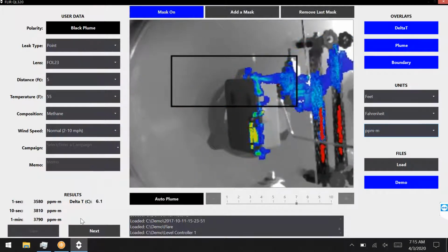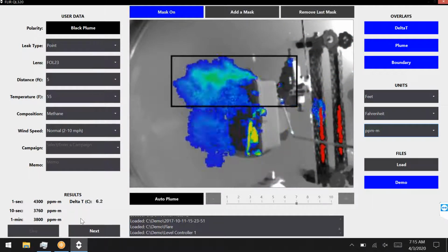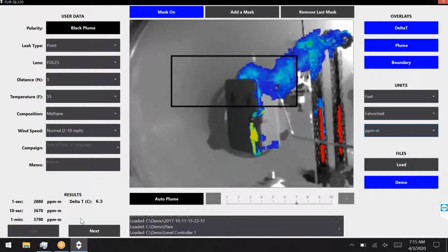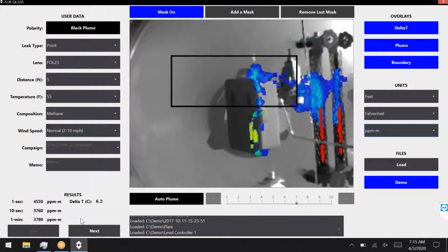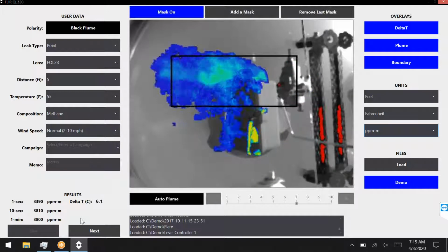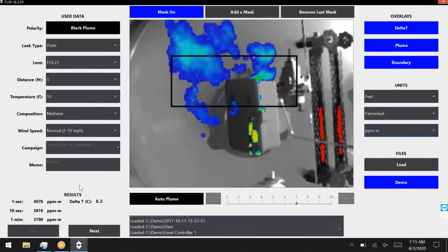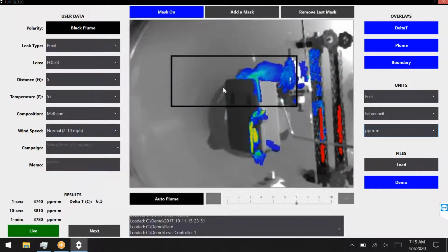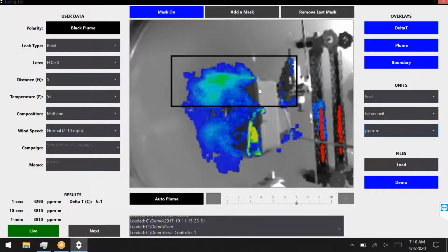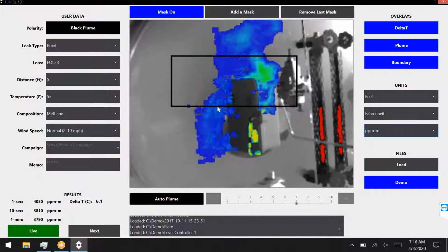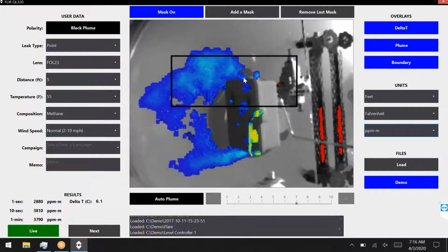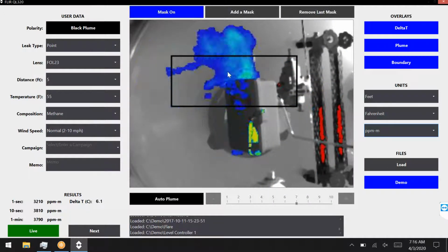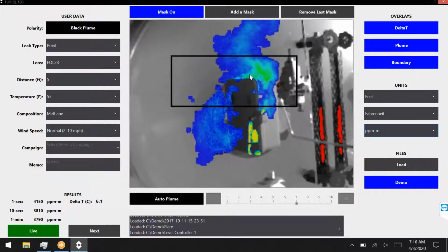With that, I don't know if you want to elaborate on that, but I really think as a demo tool for the FLIR sales organization, this video is key in helping explain why sniffers, TVAs, are inaccurate. Yeah, it sort of highlights the nature of a sniffer is a point measurement. Correct. This is giving you a concentration reading over a large area. So the reading that you get from this is not directly analogous to a point concentration measurement. But then I would say it's better in a lot of ways because it's giving you a more representative number of what's actually going on.